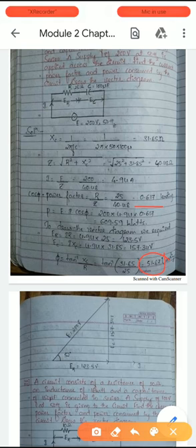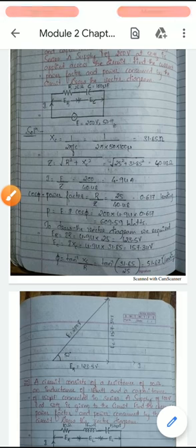So we know the value of ER, we know the value of EC, and we know phi. Then we can draw the vector diagram by taking a standard scale based upon ER and EC. As they are 123 and 157, you can take 1 cm equal to 25 volts or 10 volts, right?